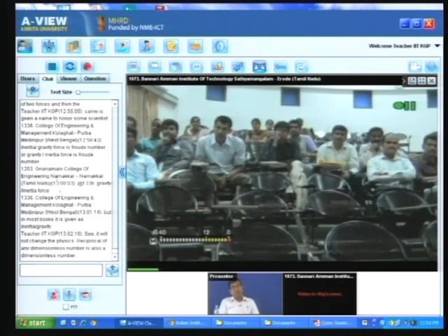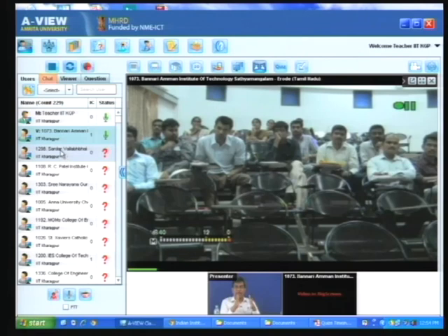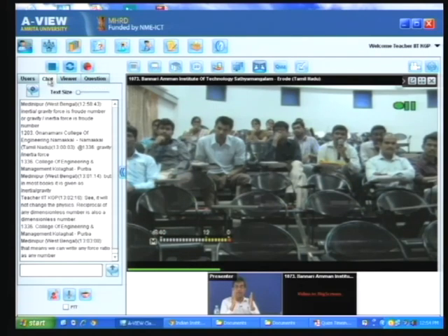However, for any dimensionless number, for example the Reynolds number, the range in which you will do the experiments depends upon the range of Reynolds number in practice. The concept is like this: I do the experiments in my laboratory. You see, any empirical results or empirical equations are always valid within the range of experiments. So, I may change the variables, but the range of the non-dimensional variables has to be the same. That depends upon the situation in practice. I cannot tell you the value quantitatively now.